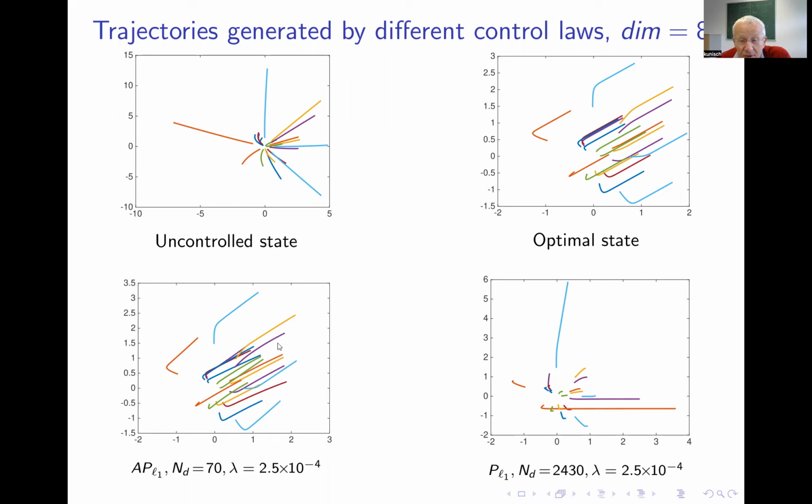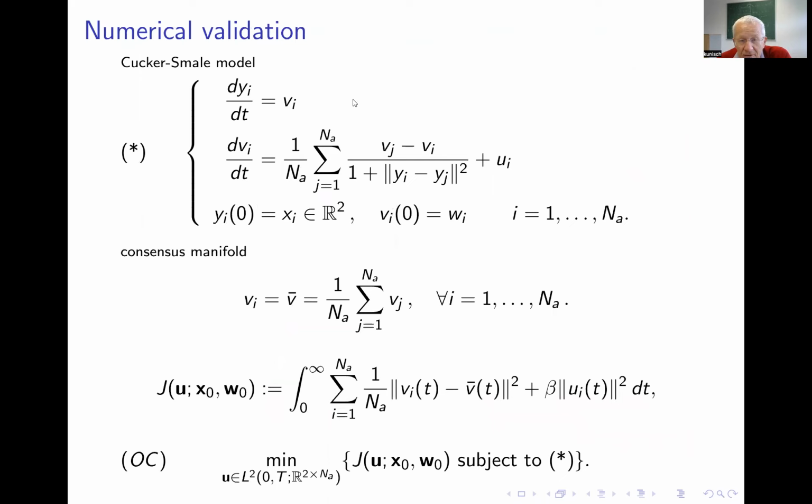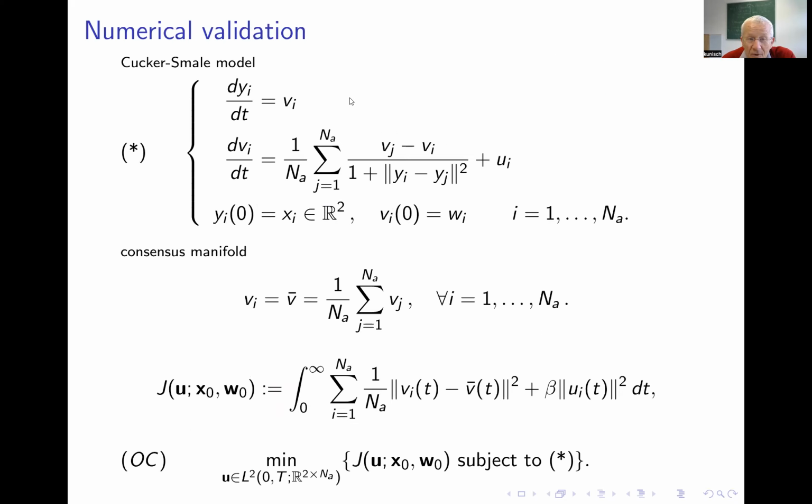This gives me also the opportunity to compare this slide on the top right and the bottom left. If you go back to the dynamical system and put noise on it, plus noise here, or here, additive noise, or noise anywhere else. If you do the open loop control, this completely fails, or it may completely fail. It's very easy to make it completely fail because your open loop control did not take into consideration the noise in the system. If, on the other hand, you do feedback and close the loop, if you add a noise